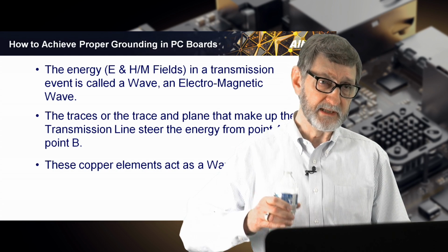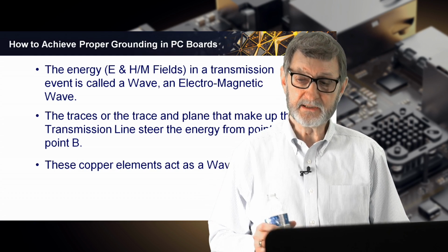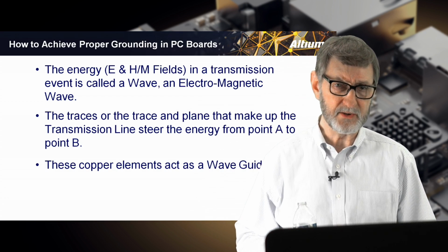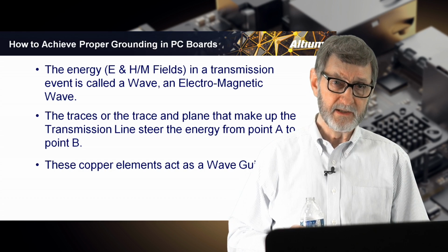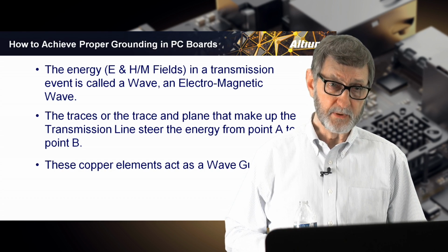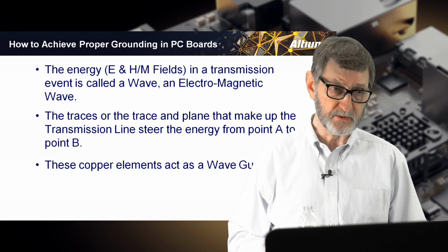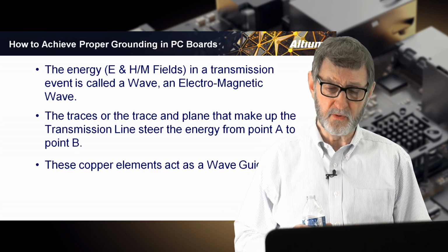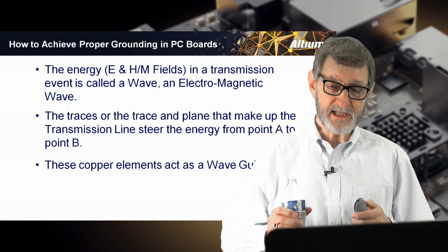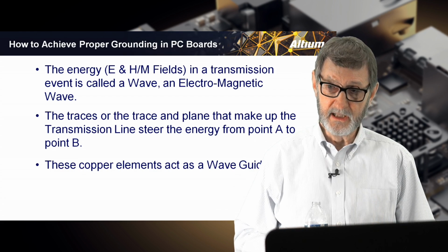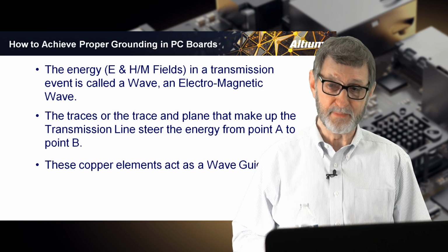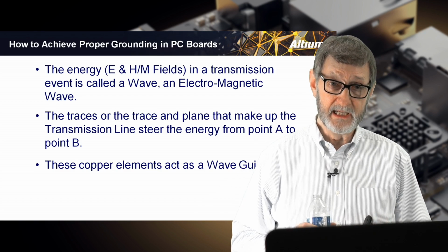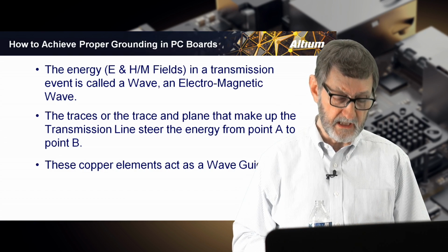And once Ralph got this concept into my head, suddenly everything that I had ever believed about how circuits function changed, and I suddenly understood exactly why everything that I'd ever experienced went wrong: because we were failing to control and contain the fields. We weren't keeping the dielectric space small enough. I have a friend, Dan Beeker, some of you may have heard him talk, where he has a song he sings, or his daughter sings actually, to the tune of Meghan Trainor's It's All About the Bass. And he sings It's All About the Space, because it is all about the space. If you aren't controlling the space, you aren't controlling the fields.